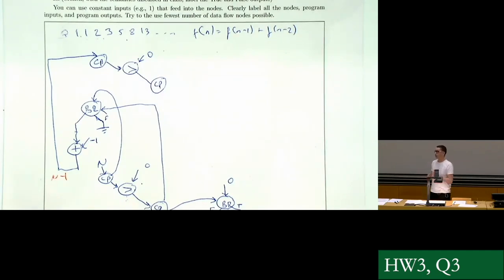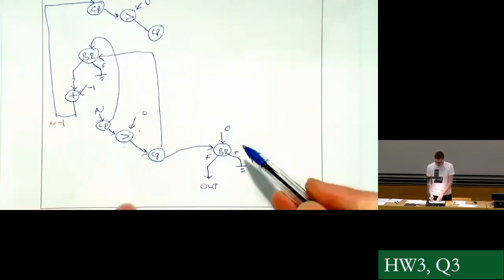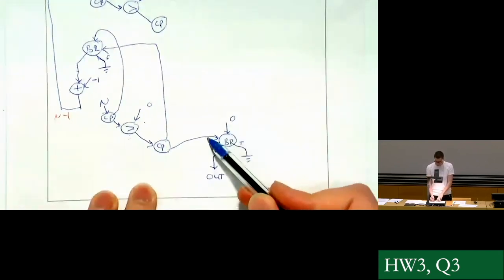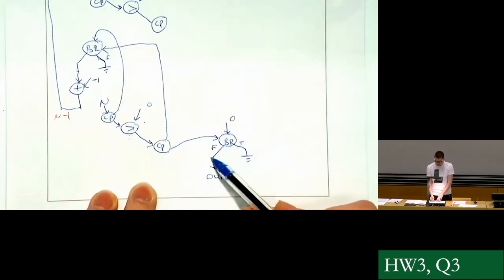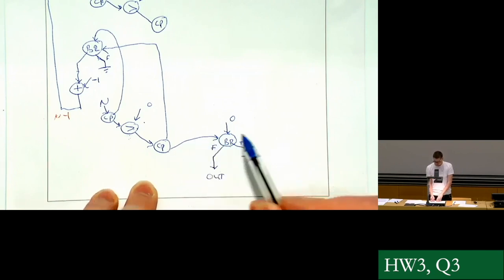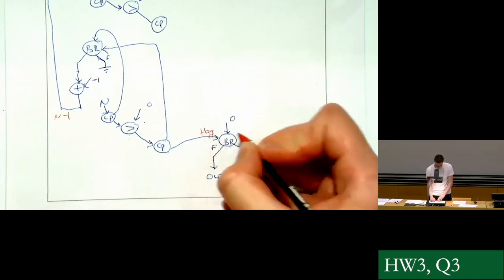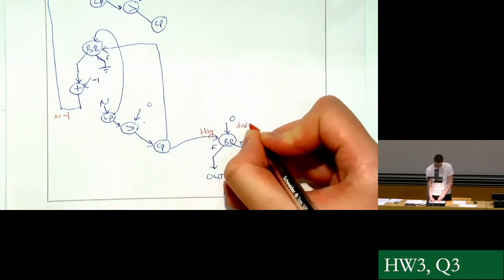Can you quickly recall how the branch node works? I don't get it here. Yeah, sure. So the branch has two inputs, right? Two inputs should be valid, and it outputs either from the false path or the true path. One of the inputs is the flag, and one of the inputs is data.